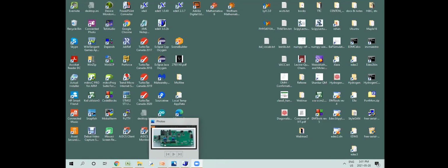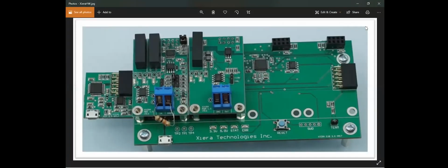This picture here is basically a close-up of the edeX hardware in the hardware system. The heart of it is a small board here on the left, which is the fuzzy logic control board. On this microcontroller, the fuzzy logic algorithms are pre-programmed onto the board. The edeX software programs the parameters for each application onto the flash memory of the chip. That's done through this small USB jack, which communicates with the edeX workstation. Once it's programmed, this little board is a ready to go fuzzy logic controller.